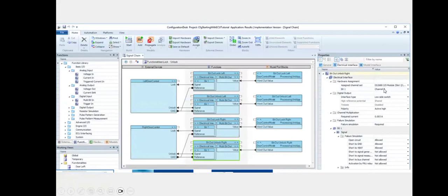What channel we have to use, and here you can see assign the channel set. We already discussed this, right? There will be IO module cards inside the hardware, so for which board we need to map, which channel we need to use, and how much current rating it has. We can do all that.